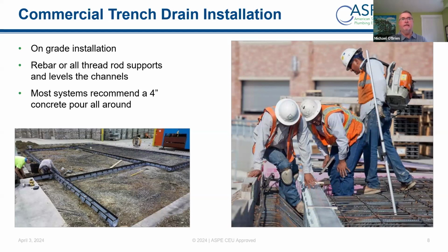And if you're tying it into another floor, you'll have sections of rebar that you need to get in. So on a 6-inch channel, I might see quite commonly at least 18 to 24 inches of excavation to put that in, to give room to get some rods into the existing slab to tie in, to give room to work underneath and get it properly supported. So again, the 4 inches underneath is a harder rule than the amount on either side. But really, you're trying to make it all part of the floor or part of the surface. So the more the better.